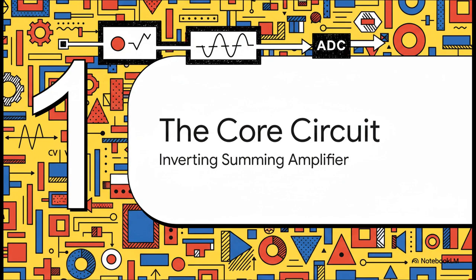And this is it. This is the heart of the whole operation. It's called an inverting summing amplifier. I know, big name, but its job is actually pretty straightforward. It takes the control voltage you're sending in, it mixes it with the physical knob's position, and then it scales that result perfectly so the module's digital brain can understand it.